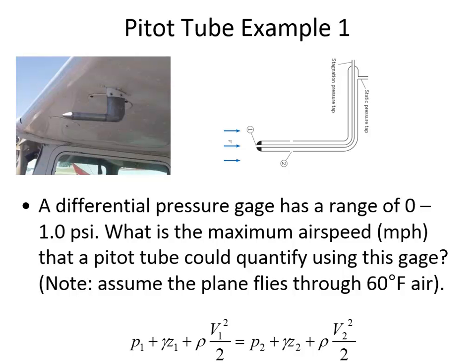Because it's taking a direct blast of all that wind. Yeah. The pressure will be higher at 1 because it is causing stagnation. The wind is blasting into that opening, whereas opening 2 is sideways to the wind. And so the force of a streamline all of a sudden stopping doesn't occur there, because it's not causing a streamline to stop. That's why I picked P1 to have the positive amount and P2 to be 0.